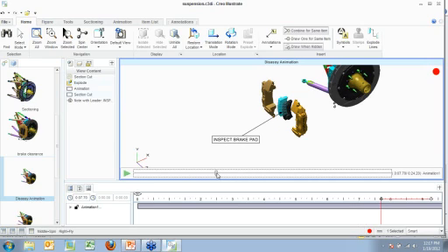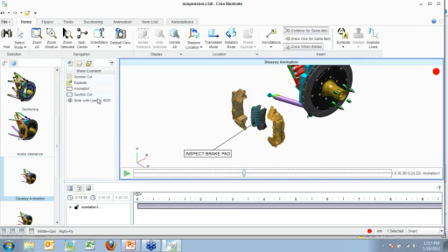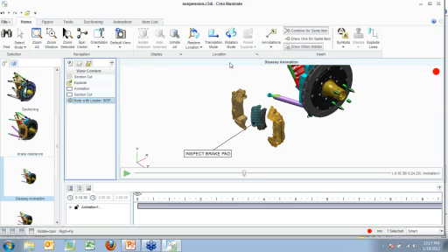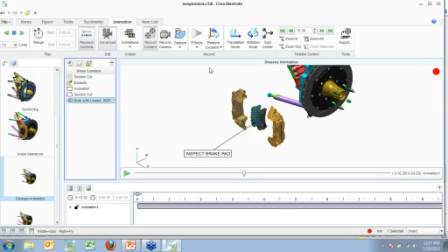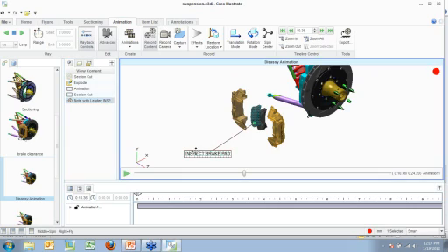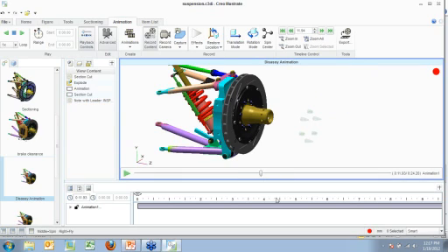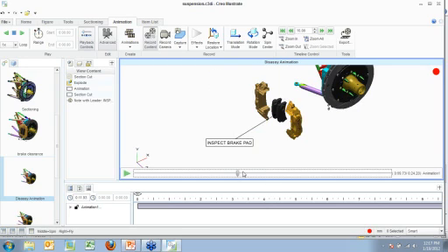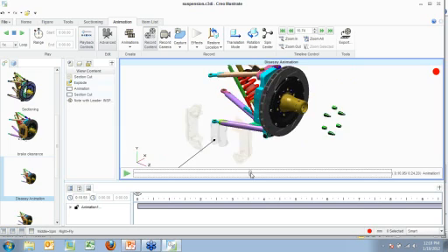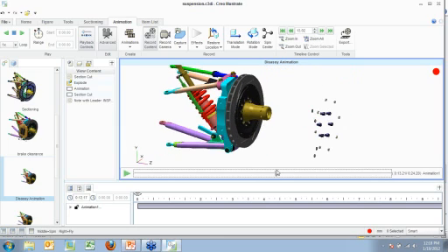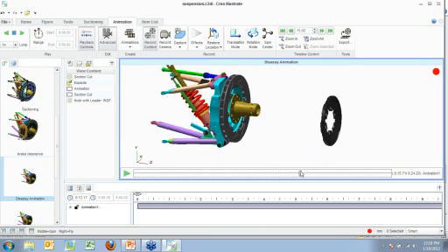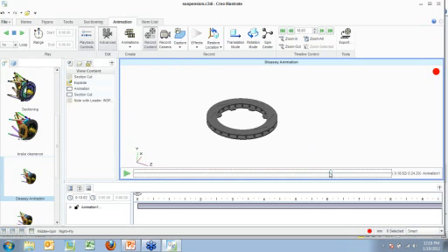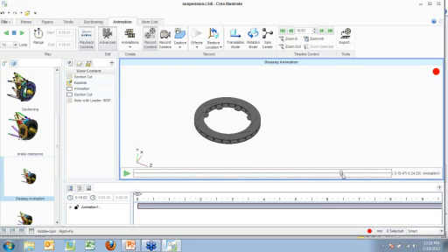So I want to let it go for a few seconds, and then I want to take this note and cause it to fade out. Let's go back to our animation tab, select the note, effects, fade out. So jump forward a second. That's how long my default translation is there. So it's going to fade out with that other part. So let's go forward a little farther. See how my bolts explode. My rotor comes out, rotates, and at this position right here, let's insert another note.